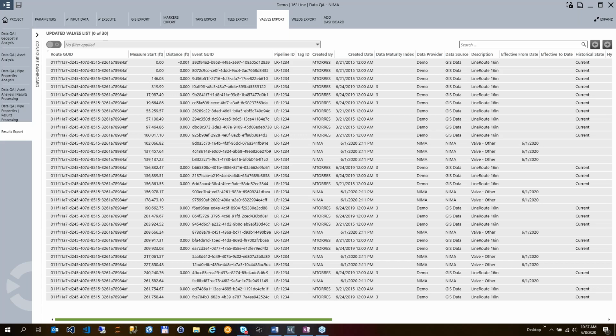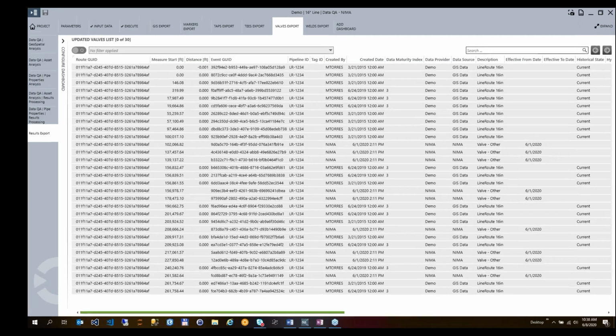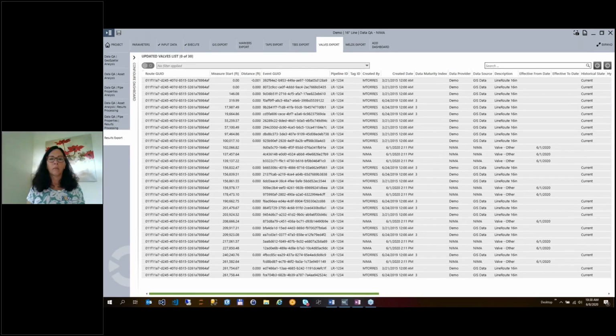And there's another question from Reynaldo where it says bom dia, and I can also say bom dia para você também. It really depends on what product the pipeline transports, but if you want to run every year and you can pay for it, it's entirely up to you. Ideally, it would be every 3, 5, or 7 years, depending on how critical the pipeline is and what product it transports.